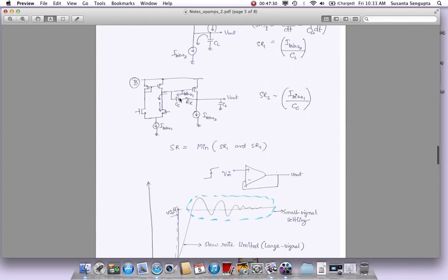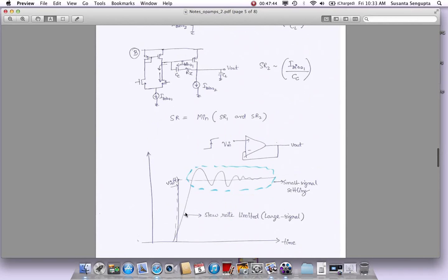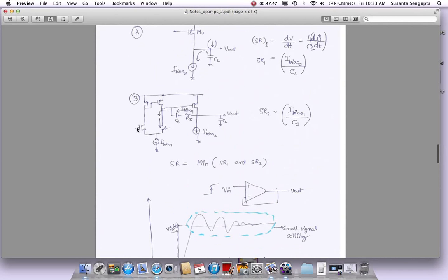So what happens is, as I mentioned in this example, we yanked this high, but this was sitting at low and it remained low, because this point is shorted to the output. The output cannot change fast because it is starting to charge up, but it's still far away. So at this point you can see this input and this input are not equal. This has gone high very fast, but this has not caught up yet. It's trying to catch up. When the slewing finishes, this catches up with this guy, so these two have a very low voltage difference.